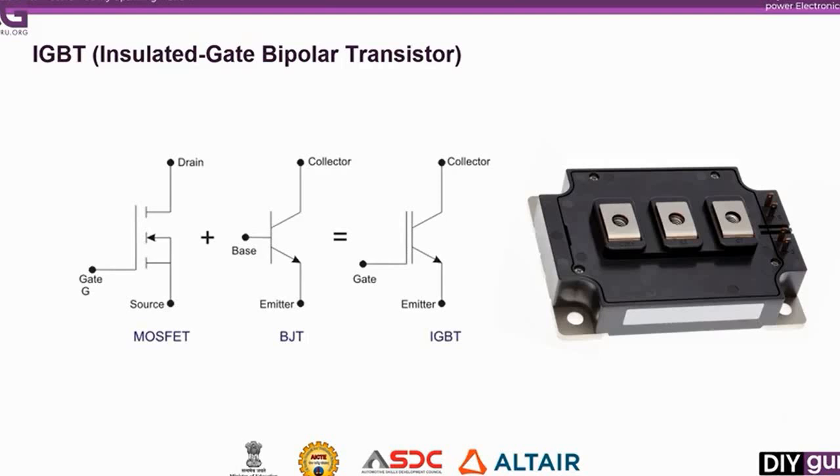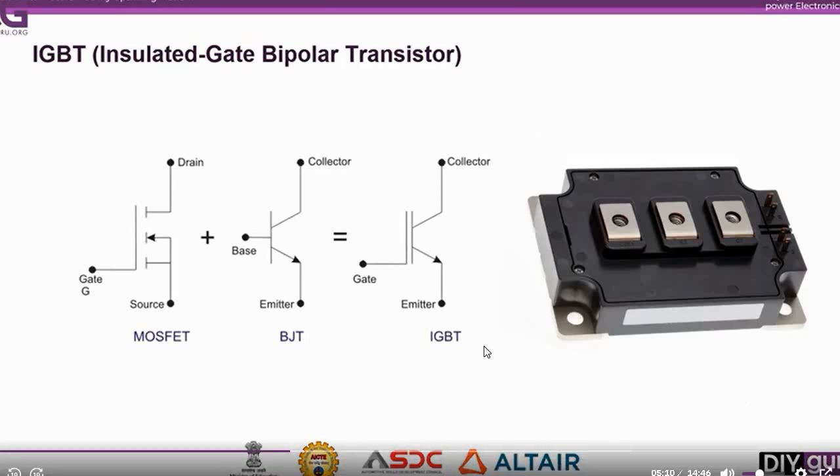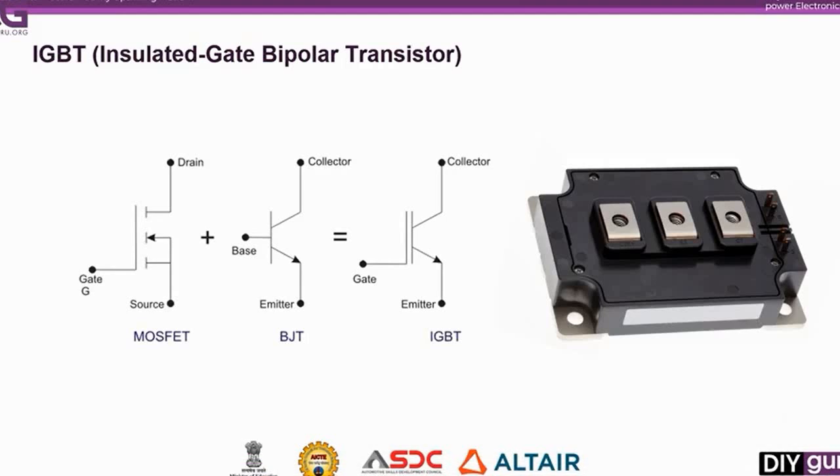On one hand, we had bad switching performance, low input impedance, secondary breakdown, and current control in power BJTs. And on the other hand, we had excellent conduction characteristics of it. Similarly, power MOSFETs have excellent switching characteristics, high input impedance, and voltage control as well. But at the same time, they had bad conduction characteristics and a problematic parasitic diode at higher ratings. Though the unipolar nature of the power MOSFETs leads to low switching times, it also leads to a high on-state resistance as the voltage rating goes on increasing.